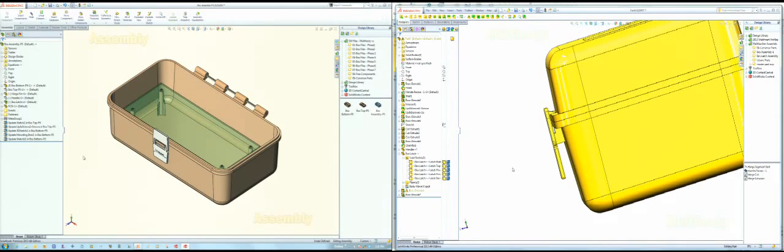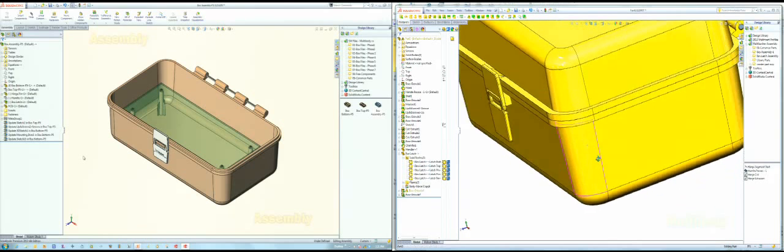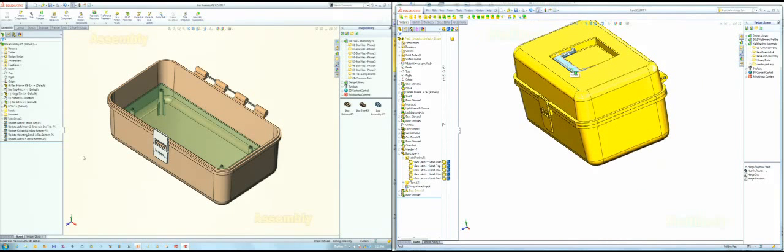Clear as mud? Yeah. On the handle, what happens if you just leave out that parallel constraint? It will actually stay right where you left it. It won't let you move it either. No. I just put that last parallel on the handle just so it would behave, but it's not going anywhere anyway. But I just didn't feel it should stay straight up like that. That's one of the major differences. You get dynamic assembly motion in an assembly, but in the parts you have to settle for some other things. We do have a few ways to make it look different, but it's not dynamic assembly motion.